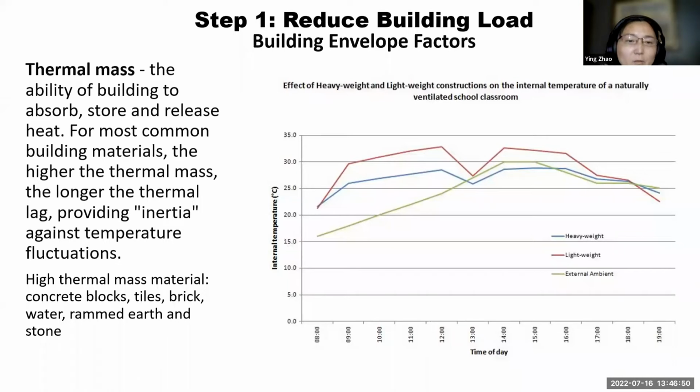So an ideal thermal mass material will have a high specific heat capacity and a high density, so it can absorb and store a significant amount of heat. And they have reasonably good heat conductivity, so the heat is able to flow in and out. It's better to have a darker surface, helping it absorb and radiate heat. So next slide.